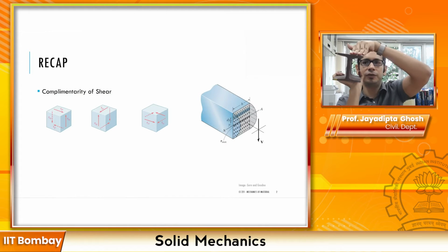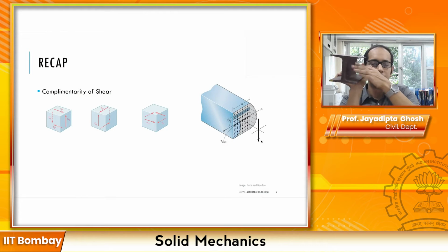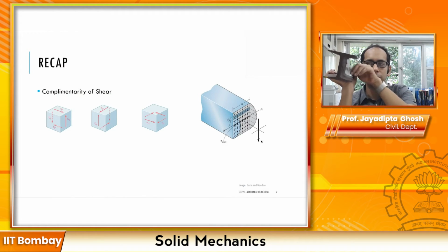So if it is free of any kind of shear that is there, that means there is going to be a negligible amount of shear in this direction, simply because here there is no shear, so no complementary shear develops over here. Similarly, in these side faces, if there is no shear externally applied, no surface load, correspondingly, since this is negligibly zero, this is also going to be negligibly zero, but you will have some vertical shear over here simply because the member is long and elongated, right?